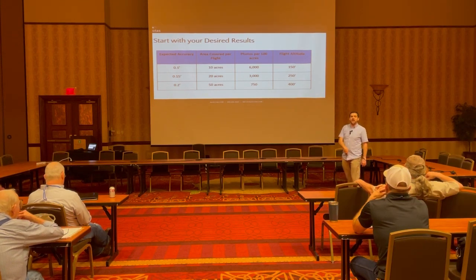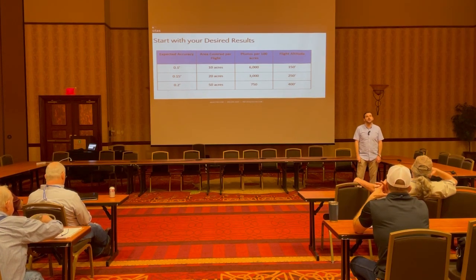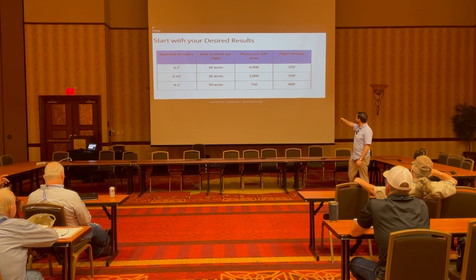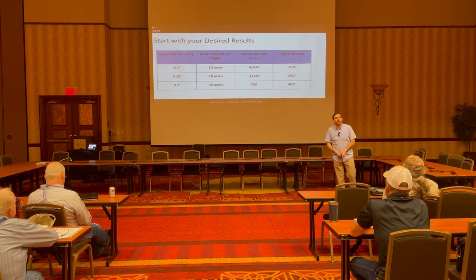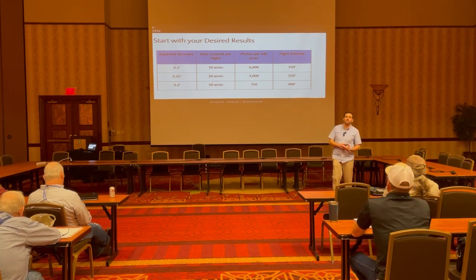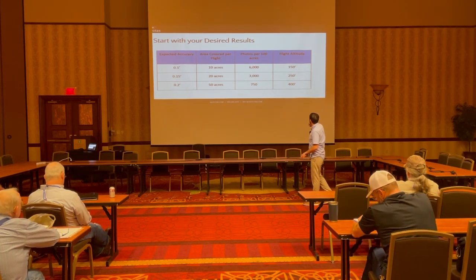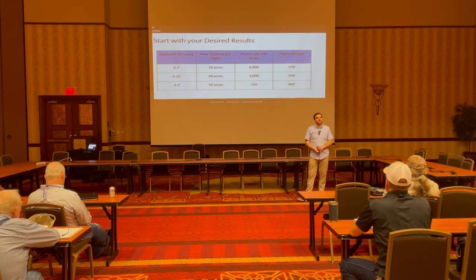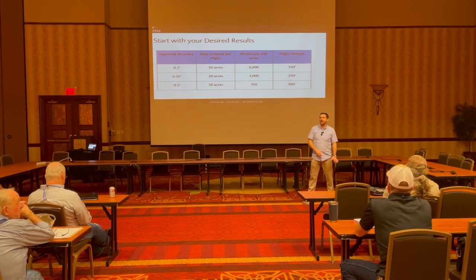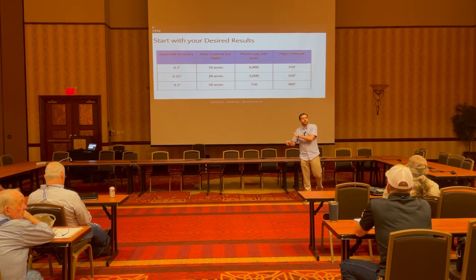If you are doing an as-built survey on a new restaurant on a couple of acres, and you want all those utilities and everything to be as tight as reasonably possible, then fly it at 150 feet, which is typically the lowest that we recommend flying. Because you're not flying 100 acres, you can get away with a little bit more data on that one and still process it in a reasonable amount of time. And for a lot of projects, honestly, 200 to 250 feet is really kind of the Goldilocks zone in terms of high enough quality data for almost all projects without wasting too much time in the field or generating too much data.